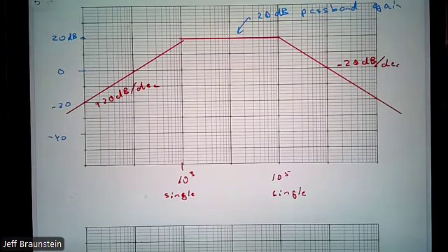We're going to build a high pass filter with a resonant frequency of 10 to the 3. We're going to build a low pass filter with a resonant frequency of 10 to the 5. That's how we get a circuit that meets that. When I say resonant frequency, both of those RLC circuits are underdamped circuits, and underdamped with a correction of -3.